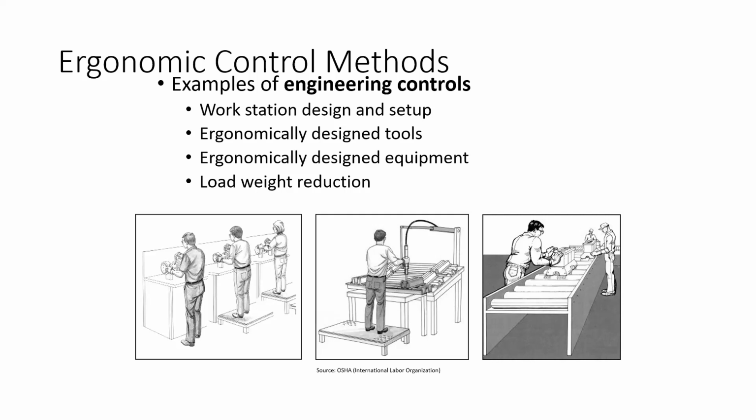Okay, you can reposition a work table to eliminate a long or excessive reach to enable working in natural postures. You can use conveyors in a main line, so the tasks are less repetitive. You can install diverters on the conveyors to direct materials towards the workers to eliminate excessive leaning or reaching. You can redesign tools or equipment to enable natural postures, okay. This is the engineering controls.